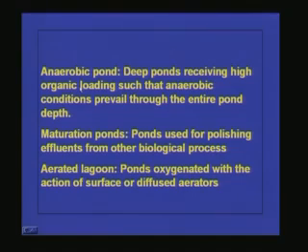For example, if you have distillery wastewater, the BOD and COD values vary from 50,000 to a few lakhs. So, we can see what the oxygen requirement is for such wastewater. If you allow it to stand in a tank or in a pond, the oxygen requirement will be so high that even though it is exposed to the atmosphere, the oxygen transfer will not be sufficient to provide any oxygen to the system. So, that is what an anaerobic pond is.